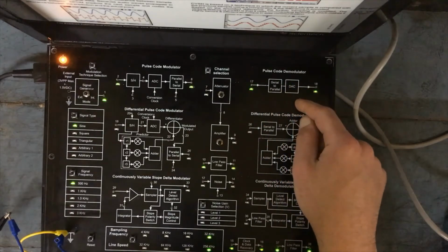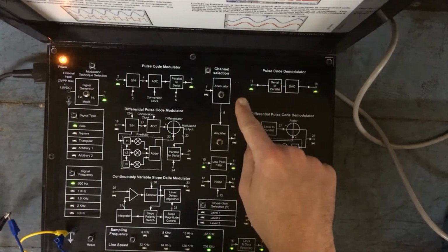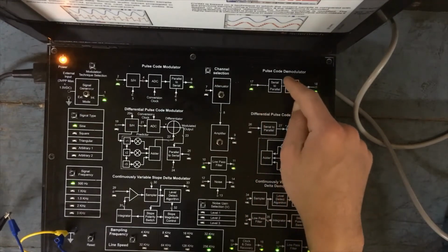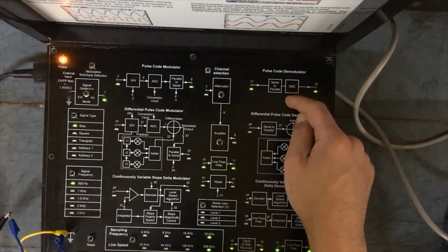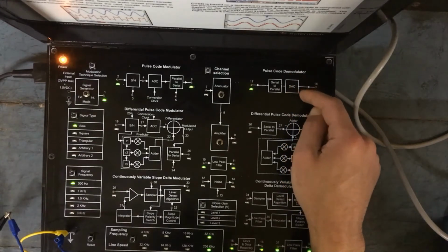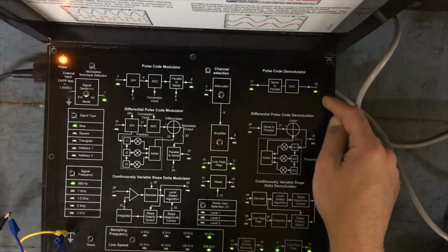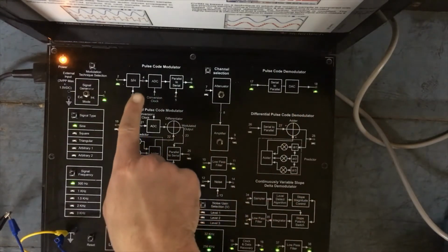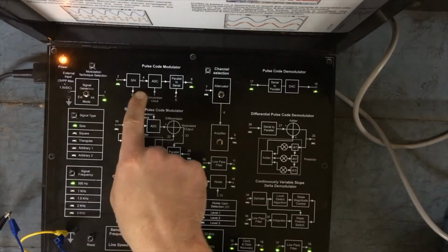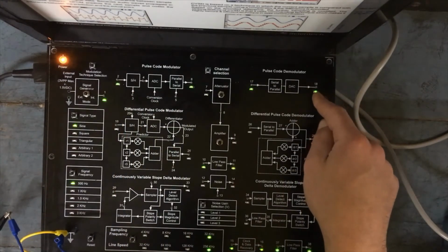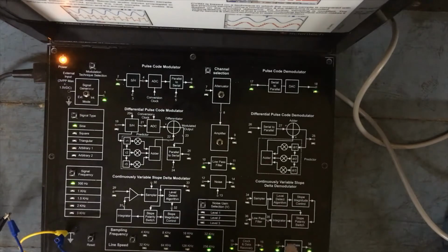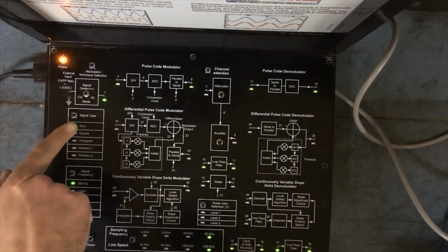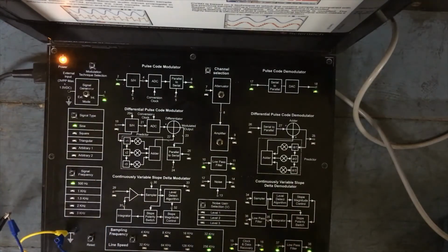This pulse code demodulator essentially converts this bit stream of ones and zeros into 8-bit parallel data output, and that 8-bit data is fed to a digital to analog converter, and finally we'll see this signal would be exactly as this sampled signal, of course, right? Now the higher frequency elements will be removed through this low pass filter, and the output over here would be the same message analog signal which we transmitted over here. This we'll see from the waveforms.